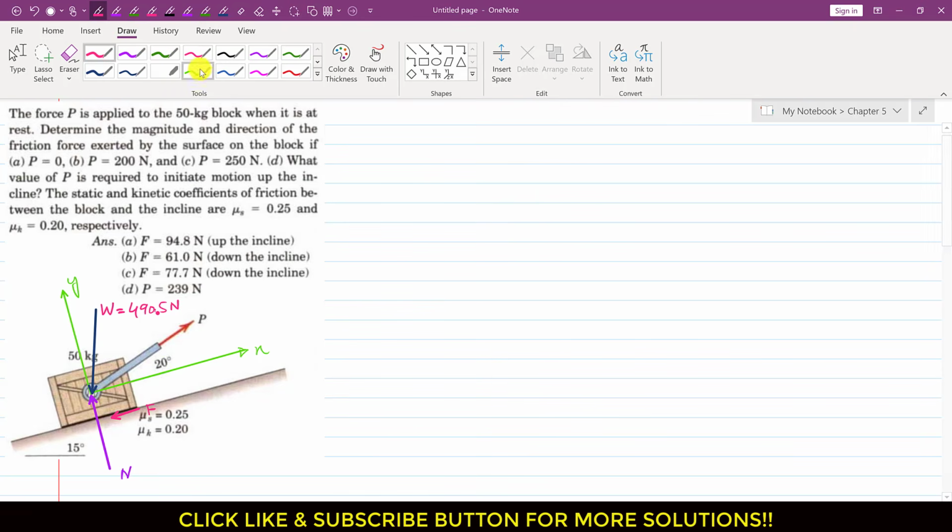So let me resolve this P force into its components. It will have one component which will be acting in this direction. We can say that this is P cos 20 degrees. And similarly, we will have one component along the y-axis which will be acting like this. This is parallel to the y-axis, and this is the sine component. So we will write that this is P sin 20 degrees.